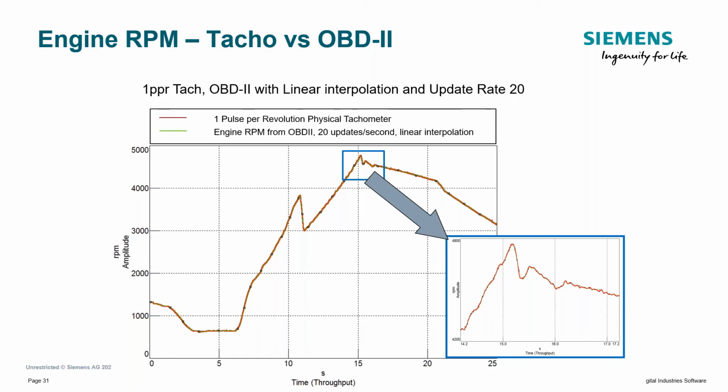Yeah. Well, if I was to upgrade to an electronic or electric vehicle, maybe a little bit of a sad thing. This OBD2, which was developed for emissions, guess what, Charles? Oh no! Don't tell me. Yeah, it will not work on an electric vehicle. It's pure electric. So that's something to keep in mind. You lose those legislated signals when you go to an electric vehicle.